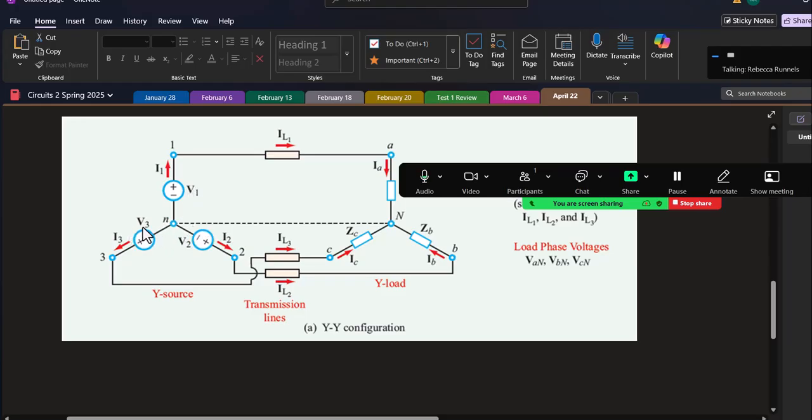They're just voltages the way you've always done them, where the value of V is the voltage on the positive side minus the voltage on the negative side. And the negative side is always neutral. So you have that set up so you're always comparing them to this neutral node. And that's going to make them different from the phase voltages of the delta source.